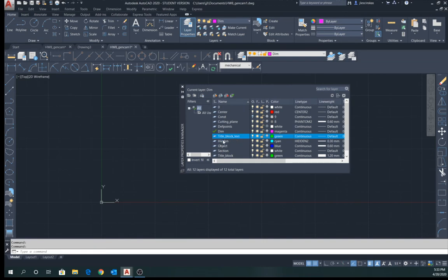So it's always capital, underscore, lowercase, underscore, lowercase. If we had 3 words or 4 words, again, we'd have lowercase, underscore, and then again another lowercase word. Okay, so once you have that title block text, you can close this out.